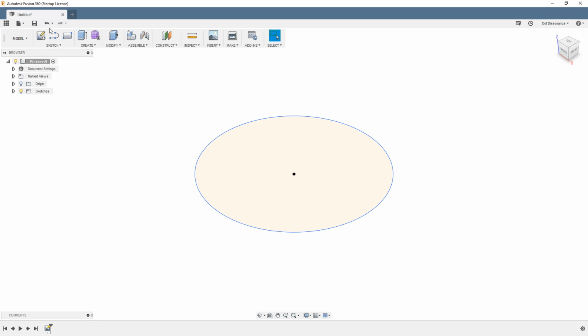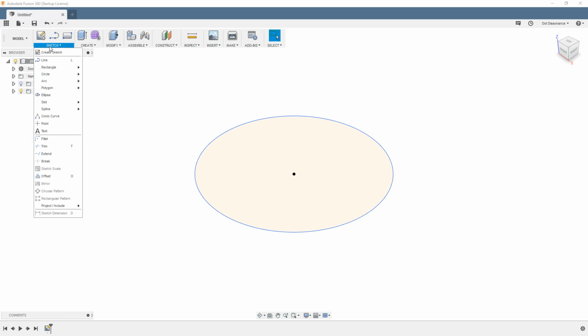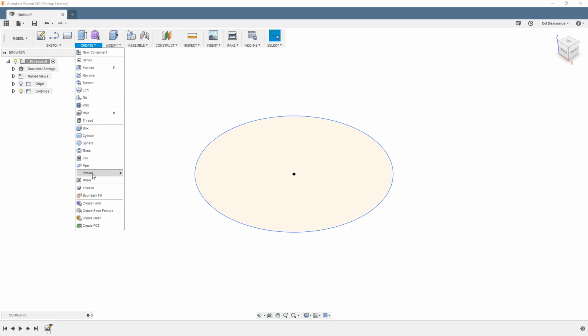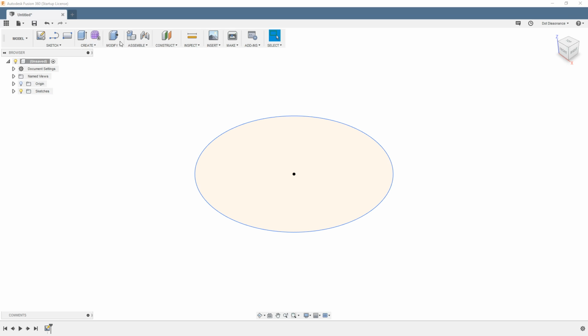And then after you've created a 2D shape, the sketch right here could be called 2D shapes or something, right? But anything sketch is on a two-dimensional plane. It gets kind of confusing because sometimes there are words like mirror and pattern that are also mirror and pattern in 3D, two different things, okay? So you do a 2D thing, and then you do some of these things right here. After I have a two-dimensional shape, I have to create a solid thing. After I create a solid thing, then maybe I could modify it. After I'm finished doing these things back and forth a bit, maybe I could make separate parts, and then maybe I could assemble them. That's kind of how the flow goes.